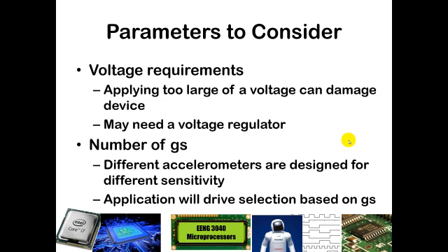And so the accelerometer boards that we will use have an onboard voltage regulator to ensure that we are not giving too much voltage. In fact, that voltage regulator will allow us to drive an accelerometer that relies on far less than 5 volts with a 5 volt input signal, so we don't need to produce a different voltage than what we can get from our standard USB signal.